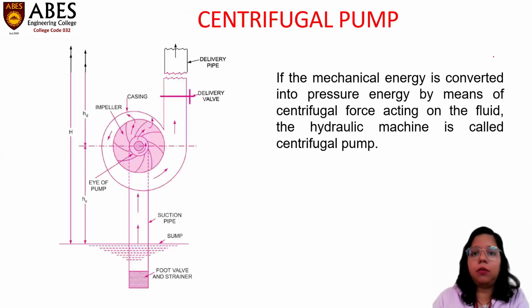In the AKTU syllabus, two types of pumps are included. One is the centrifugal pump, and the other one is the reciprocating pump. These two pumps are covered in this lecture. So, what is a centrifugal pump? If the mechanical energy is converted into pressure energy by means of centrifugal force acting on the fluid, this type of hydraulic machine is called a centrifugal pump. Here is the diagram for the centrifugal pump. The centrifugal force is used to convert the mechanical energy into pressure energy. That is why it is called a centrifugal pump.